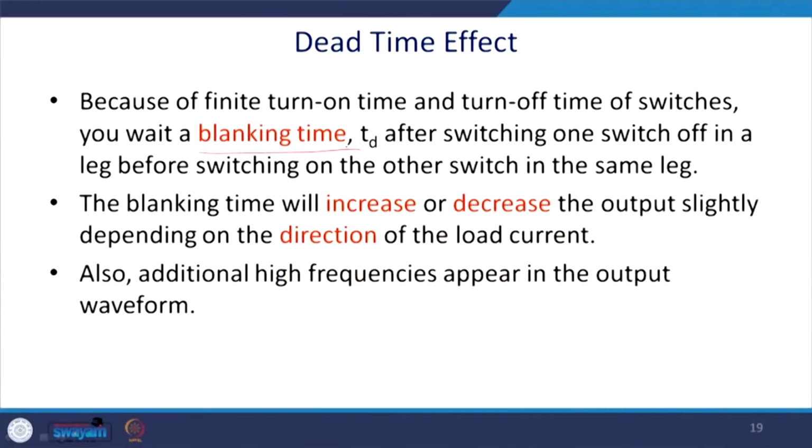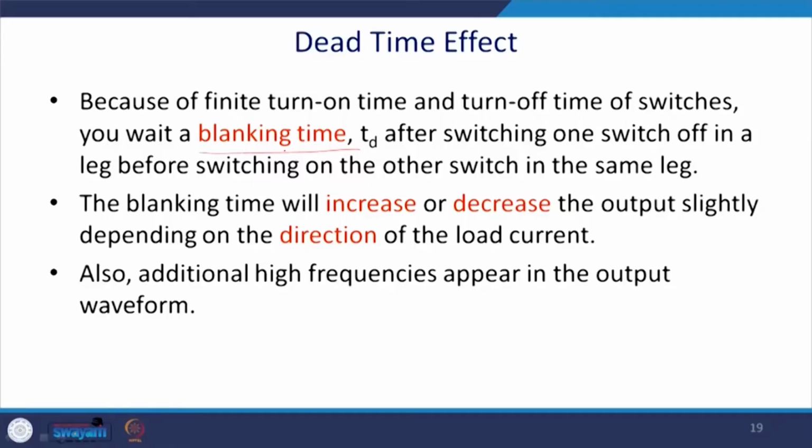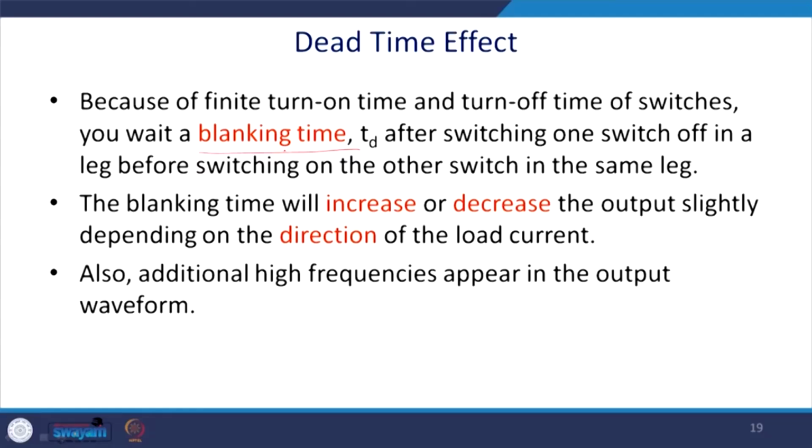Another important issue we require to discuss: I know a student required to implement this active rectifier, power quality conditioners as a hardware, at master's level or the BTech level. So, we require to deal with the switches. Because of the finite turn on and turn off time of the switches, you wait for the blanking time.